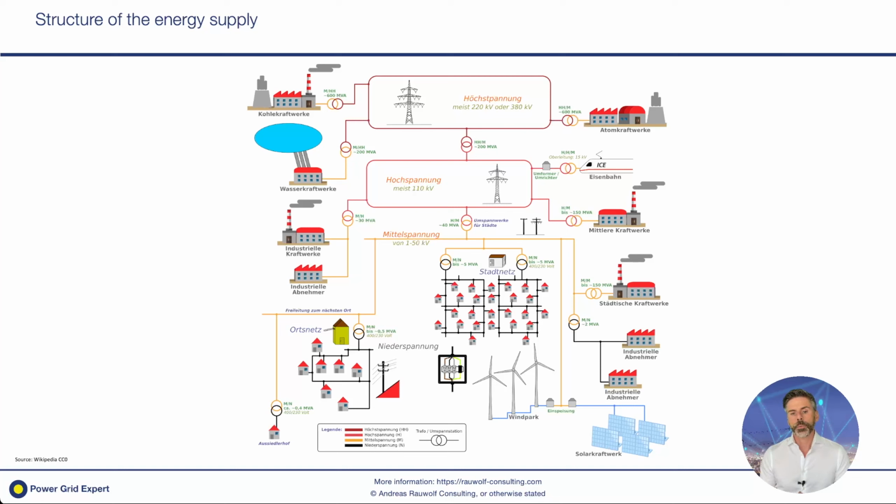And at the feeder, we have the so-called substations. The substations are small transformer stations with a transformer transforming the voltage from a medium voltage level down to low voltage. If we talk about low voltage, it's still 230 or 400 volts, which you might still consider high voltage, but electrotechnically speaking, this is low voltage.